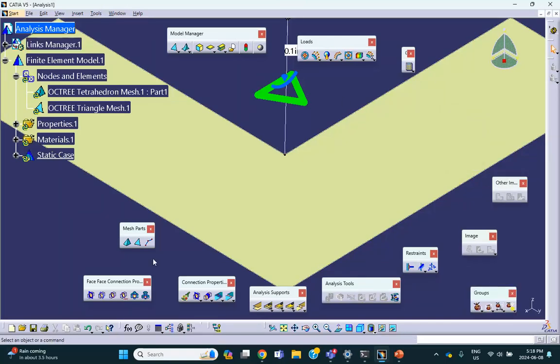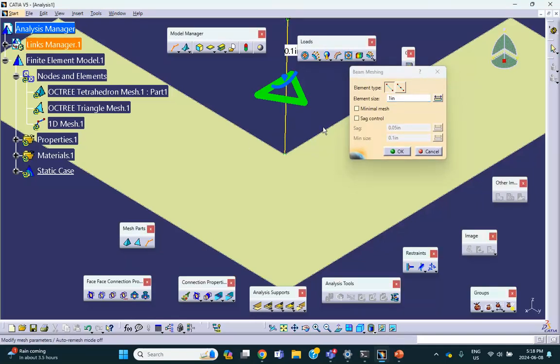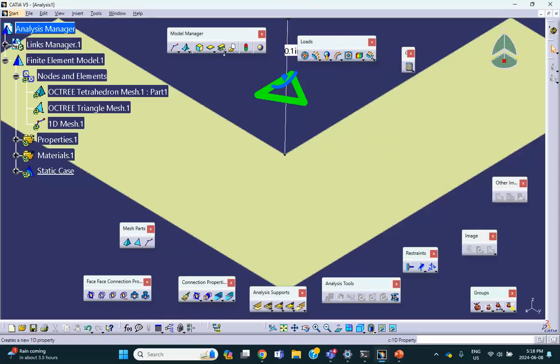So here's the beam measure. You click on that. Maybe I'll make it 0.1 because remember, one is going to be a couple, at most a couple of elements. I'll use more of them. Maybe 0.2. How about that? 0.2. All right.